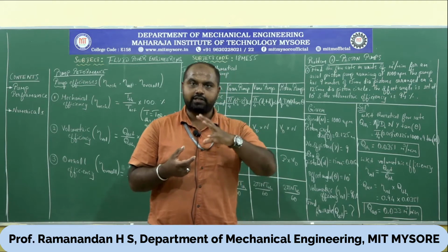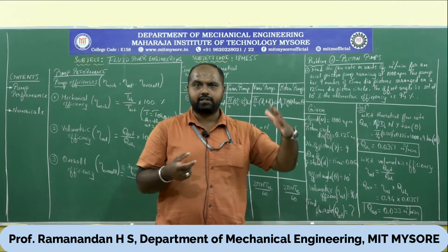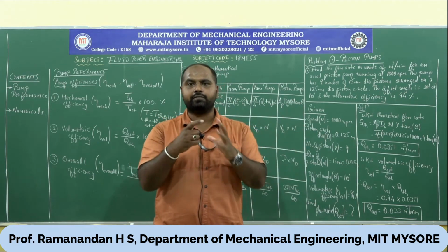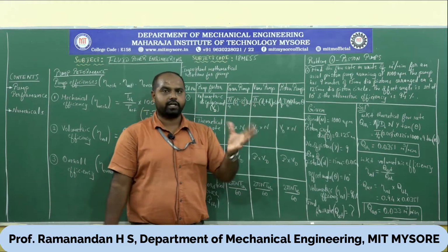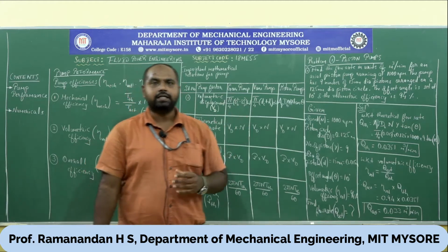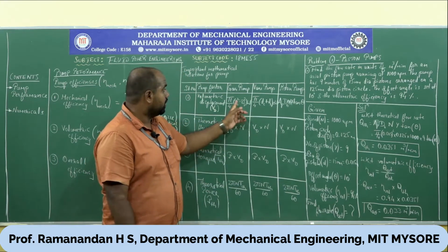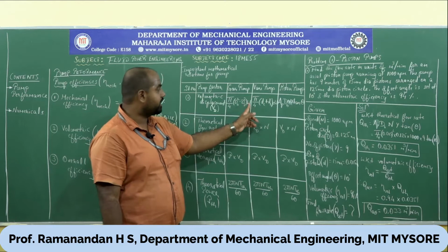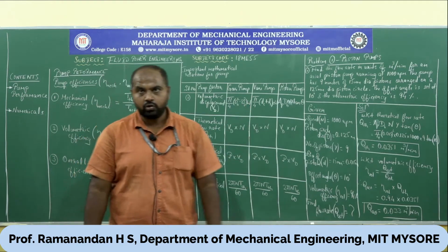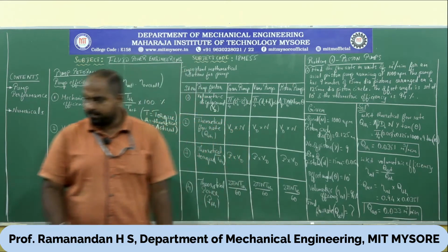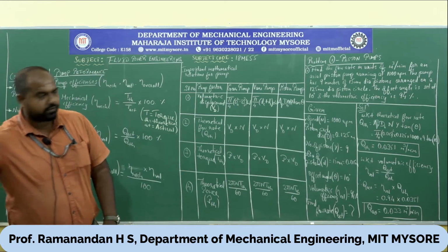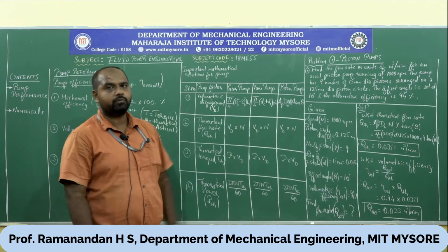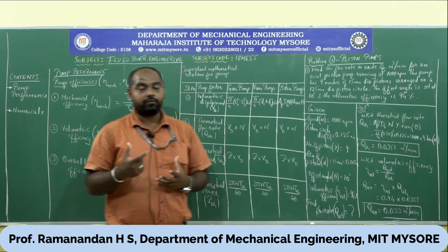We have seen external gear and internal gear pumps, which are a combination of gears. So it is the largest gear minus the smaller gear, or outer gear minus inner gear, the squares of their diameters into W, where capital W is the width of the tooth of the gear. So W is the width of the tooth of each gear.